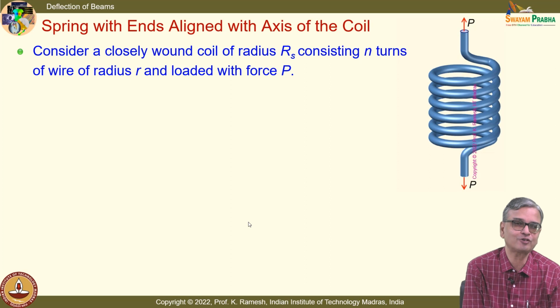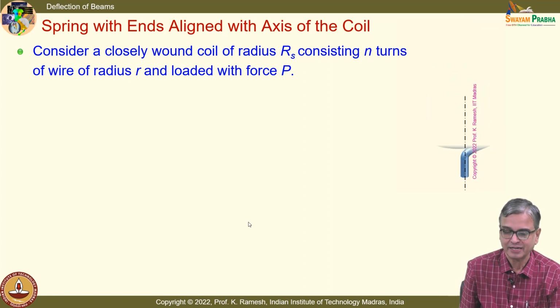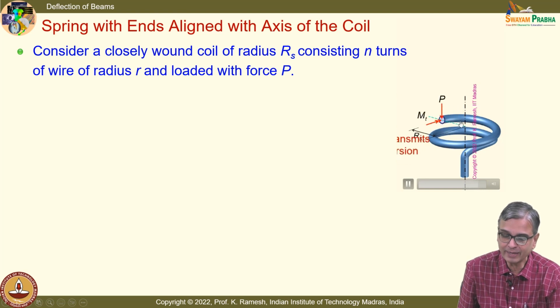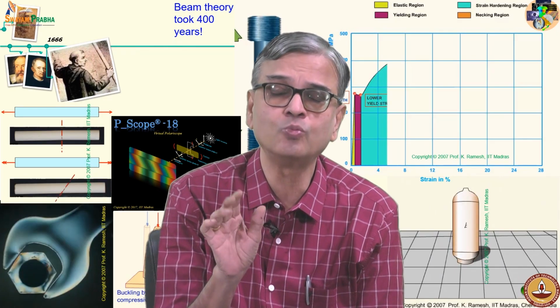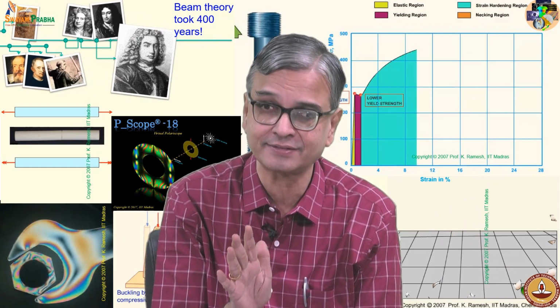Now let us go back to the classical problem. You take a simple spring, and if you find out what is the force that is acting, follow this animation very carefully, because I would translate this by transmissibility. Nothing happens. Only when I move it to this point, I also have a twisting moment acting on the spring. It's very important. One of the aspects I find is how to move a force from one point to another point. You have to master it.